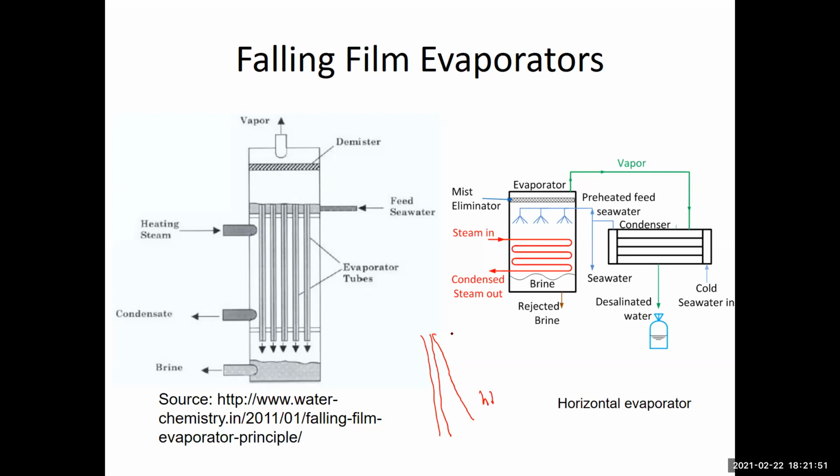So the value of H starts high, and then it keeps on decreasing as the boundary layer thickness increases. Not like here. In this one, you have a high heat transfer coefficient here, and it decreases with this boundary layer. And then the tube is finished. You go for another one.